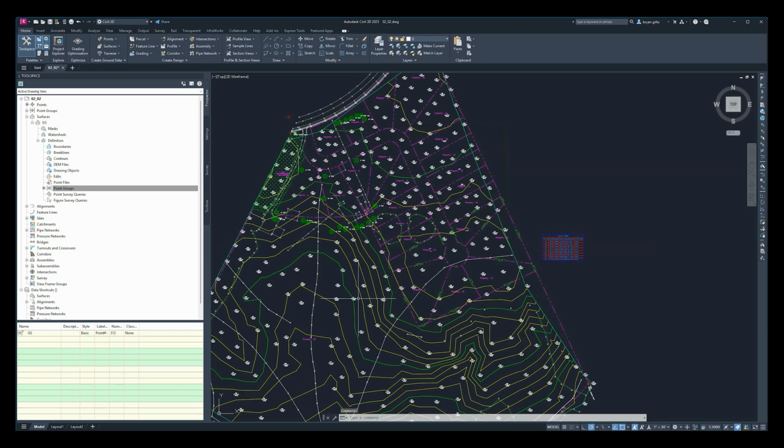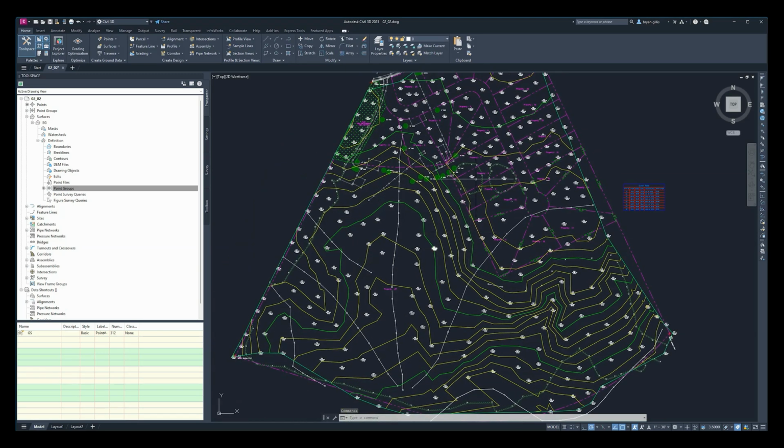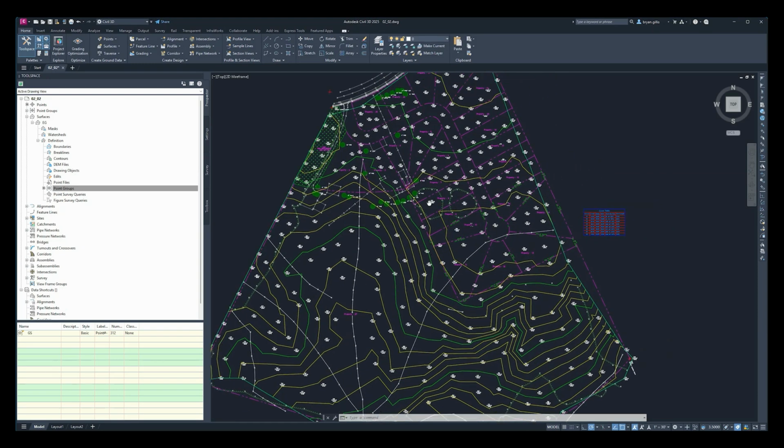And then here you'll see we have our contours automatically generated. If they didn't automatically generate, go into the command menu, type RE for regen, and then press enter, and that will help your contours show up. So just like that, we've gone over defining surfaces with certain types of data categories and different methods for adding and editing the definitions of our surfaces.